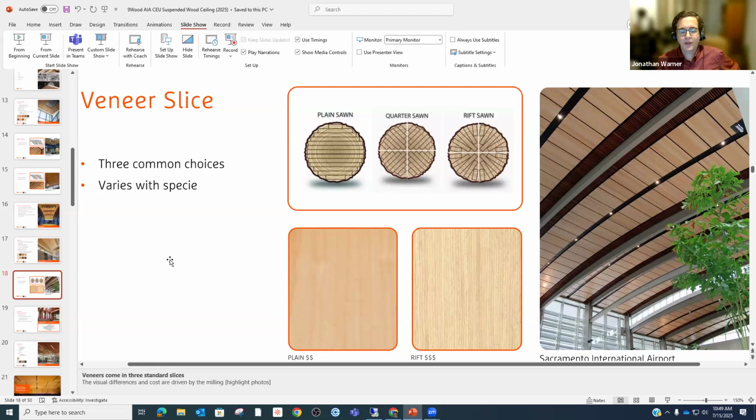I would think both could be a potential option. I think as you get deeper, and I apologize if I'm not understanding your question correctly, Ruben, but if it's like a box frame around some type of acoustic panel, if it's really deep, at some point a veneer would be a better option. As you get to wider and wider solid wood, especially beyond 1x6, it can be more prone to having issues and tolerance issues or prone to warpage. Whereas the veneer can, if you have a 10-inch deep or whatever, be a better option.